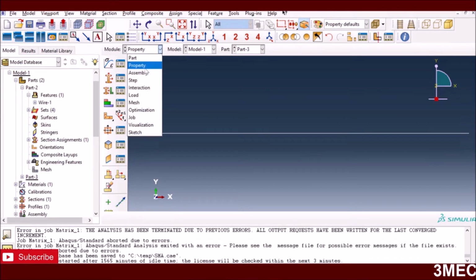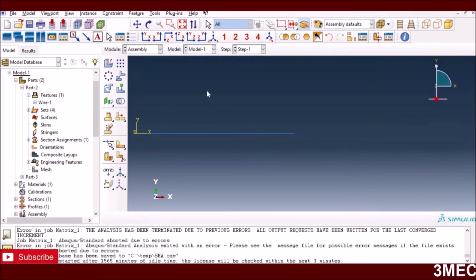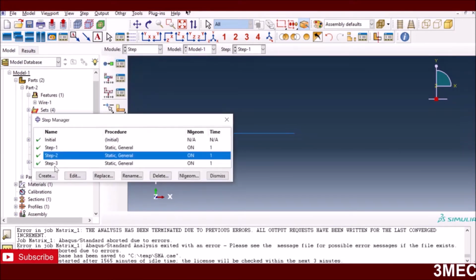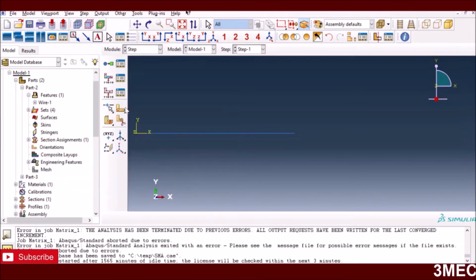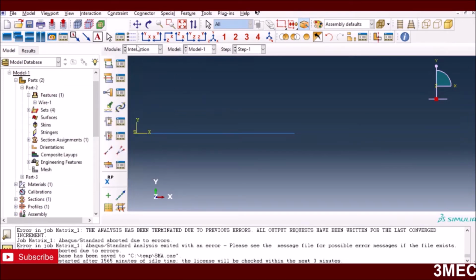And next is the assembly module. I can instance the part here, which I already have done. So this is here, just click on this and bring it here. Okay, so that's already there. Now I go to the step and I create a general step. I have 3 steps here because in their case it was loading, then unloading, then heating, and then relaxing. I'm just leaving it like that for the time being, but I will explain those once we reach the next step where we have the main matrix as well. For the time being, just consider you have 1 step. There is no interaction because it's just one component here, which is a fiber. So I leave it like that.